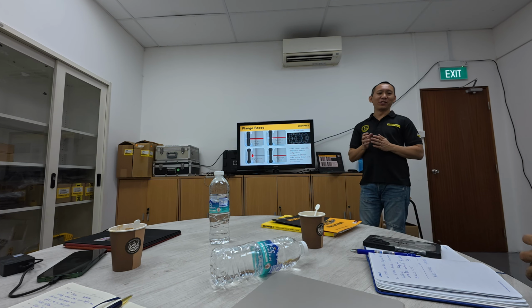So what is a bolt? Okay, so a bolt actually behaves like a spring. It actually follows very much Hooke's law. Okay, so when you do torquing or stretching, you will go into the elastic range first. Then when you hit the plastic range, it will start to deform. Then of course when the bolt fails, at the tensile bond, it will snap. So basically you follow Hooke's law. It behaves like a spring. When you stretch the spring too much and reach the tensile limit, that's where it will snap.